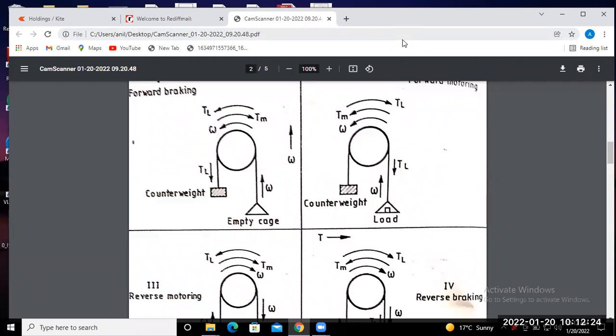So here we are discussing the motor speed characteristic in different quadrants. That means in all the four quadrants, whatever is possible. Okay. So the first quadrant operation is known as the forward motoring mode. In forward motoring mode, electromagnetic torque and the speed are both in the anti-clockwise direction. That means both are positive, and load torque is in the opposite direction of the electromagnetic torque development.